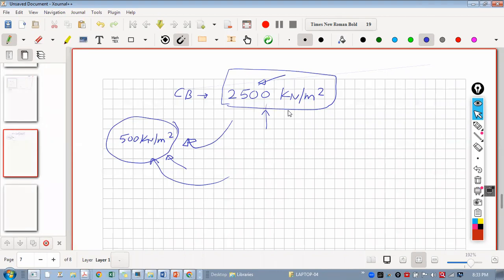See what happens. As for this data, whatever we are getting, first of all, we are getting it from the sample bore logs, right? That means it is a sample. Once we take the sample, it is not necessary that in all the area this will have the same SBC. It depends on the area. If we have more area and the samples are less, then I will not go for this value. Then I may think of having 2000 something or 1800, whatever. Depends. If we are having enough samples for that area, then definitely this value is okay to take.